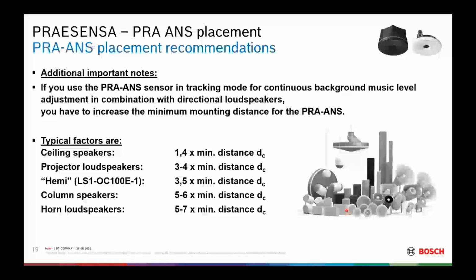And here you can use the settings for the noise sensors in PRAESENSA, where you can define how fast the level should decrease or increase, and how much it should decrease and increase. So all these parameters for how your used signal shall be influenced based on the noise can be set in different parameter settings.